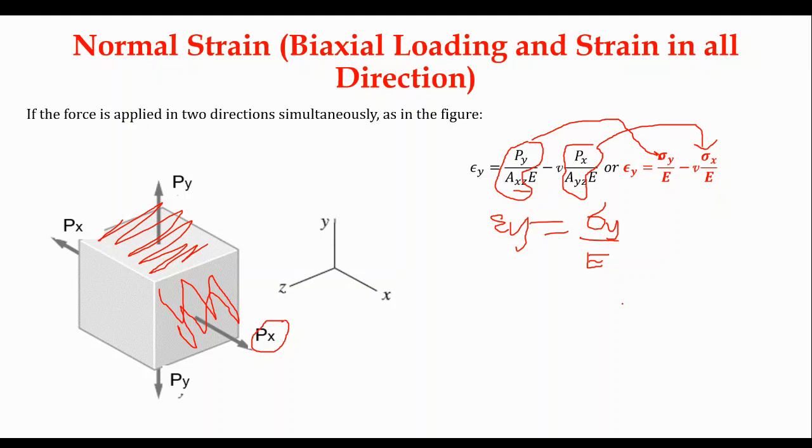But, you also remember nga naay stress ni x? So, how do you convert the stress in another direction to your direction? Una, multiplyan nimo og Poisson's ratio para ma-convert nimo si stress ni x over E. Para pwede nimo siya ma-apply in your own direction. Nagets ninyo ang thought? So, maski wala ka ka-memorize, you can actually derive it.